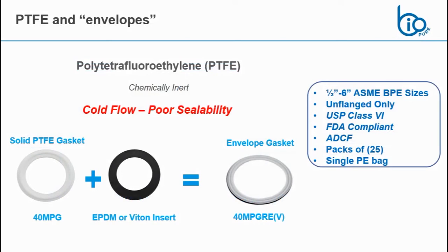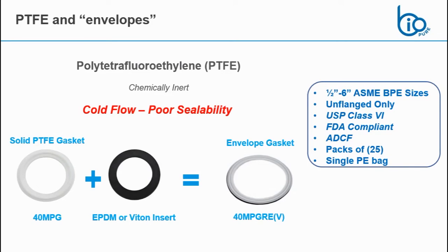So a little bit about PTFE, okay? PTFE gaskets are used in many applications. They are out there, and as you know, when we discussed, PTFE is one of the most inert and most pure compounds available. So it's often used in places where ultimate chemical resistance or high purity, ultra high purity is required. However, as a gasket, PTFE does not make a great seal, and it really requires more care and more attention to installation and more regular checks on the installation and clamping torque than a rubber-based gasket. So it's more prone to leakage, especially during wide temperature variations.